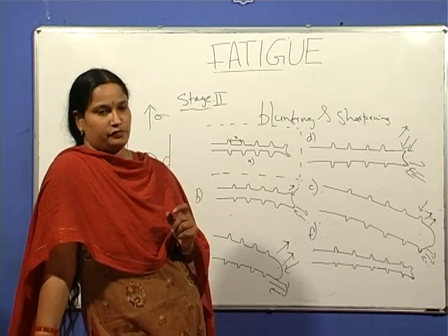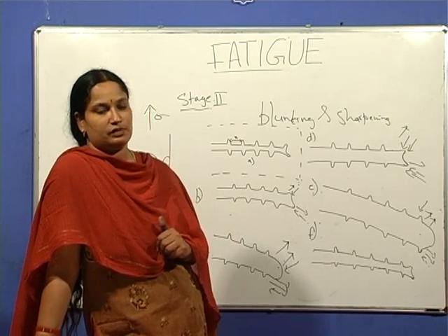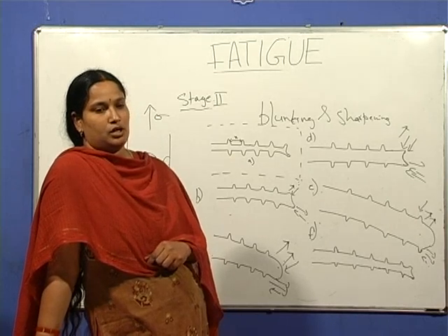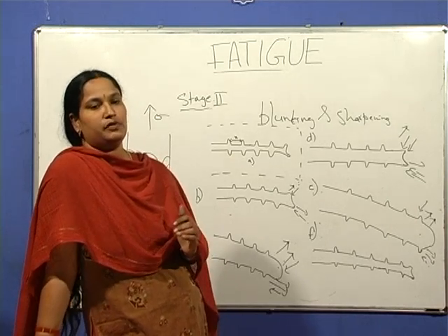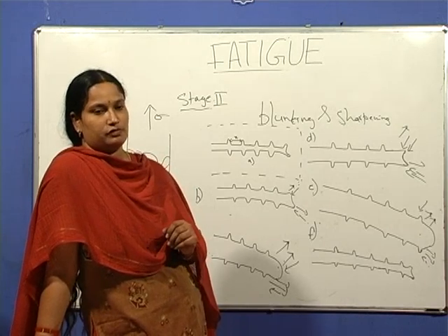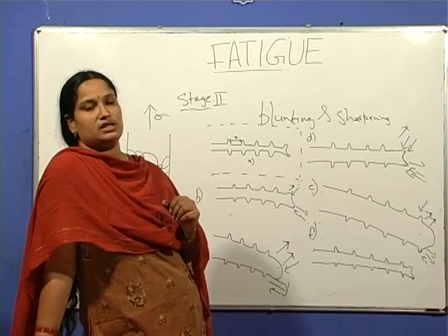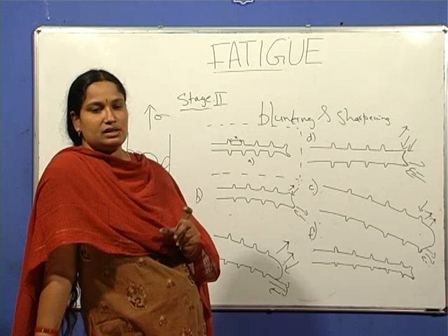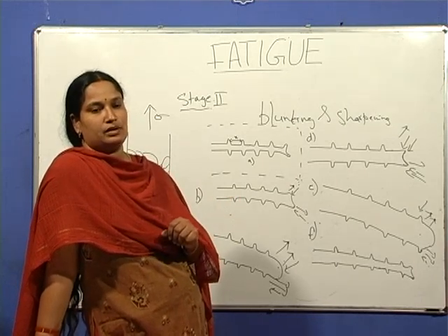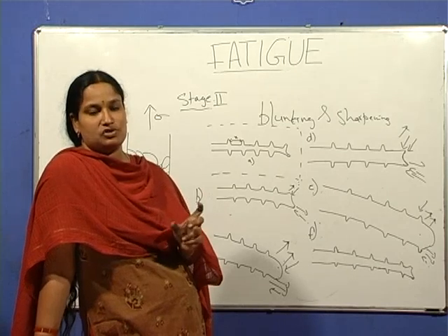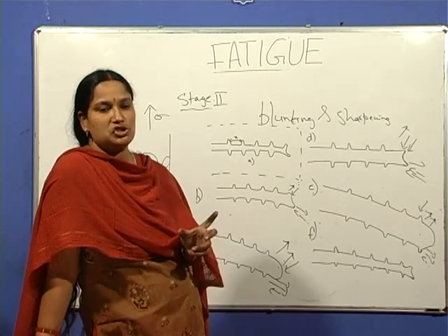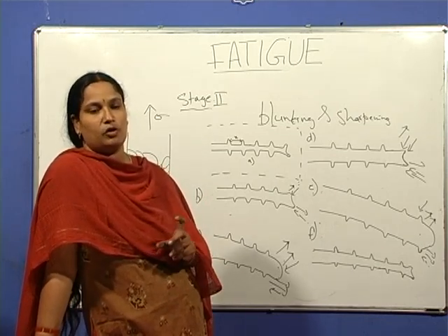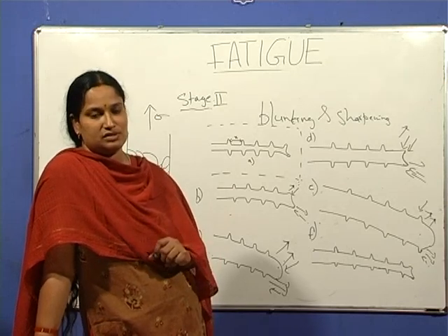For the case of fatigue, the fatigue strength or fatigue life is lowered due to the presence of these stress concentrators. The fatigue strength of a material, when stress concentrators are present in the specimen, can be evaluated by testing a notched specimen. By comparing the SN curve, stress versus number of cycles to fatigue curve, for notched and unnotched specimens, one can assess the fatigue life of a component in the presence of these stress concentrators.